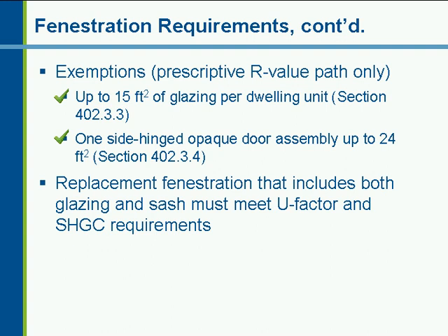One final comment: any replacement fenestration that includes both glazing and sash must be brought up to code. I mentioned earlier that if you replace only the glass, you're not required to bring it up to code, but if you replace glass and the sash, you must.